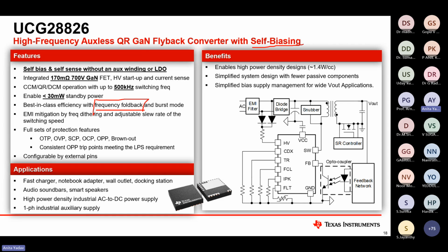Instead, it goes into a hard switching kind of mode, but at the same time it goes to a very high number of valleys at the end. This is called valley switching, but instead of switching here, it goes like this, and it starts switching here.